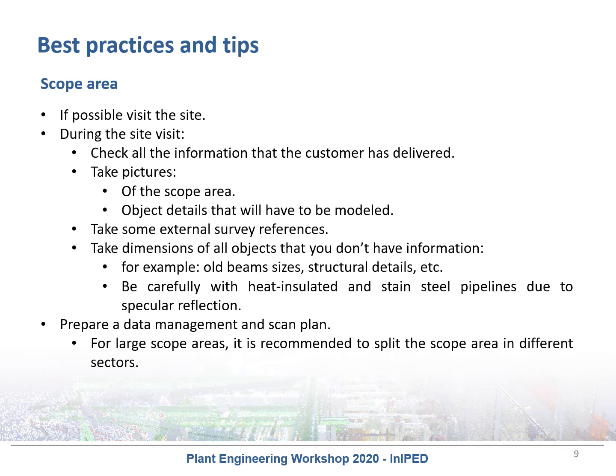Also, you should take pictures of all object details you have to model and the scope area. I recommend you take your time on that point. You will need it as a support while you are creating the 3D model in your office. It will save time and effort. Also, you have to do all the measurements of the objects for which you don't have information. For example, all beams, structural details, vessels, equipment, and constructor details.